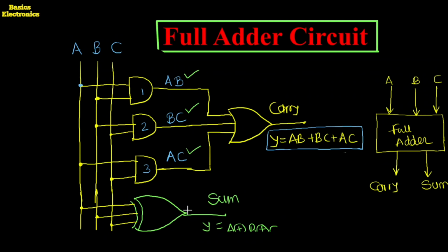Okay, here if there is a question, then the writing sequence is same as that of the previous full adder. What we did in the previous full adder, first we wrote the logical statement or the meaning of the full adder. After that we wrote the construction of the full adder. In that you have to write down the full adder is constructed by using three AND gates, one OR gate, and one 3 input XOR gate. The 3 input bits are there.